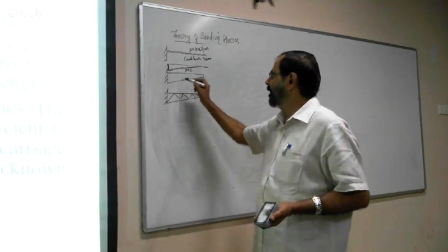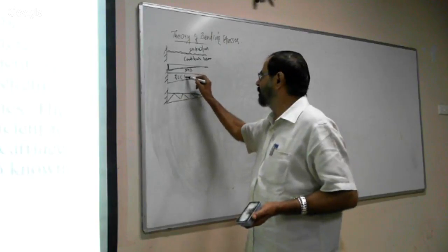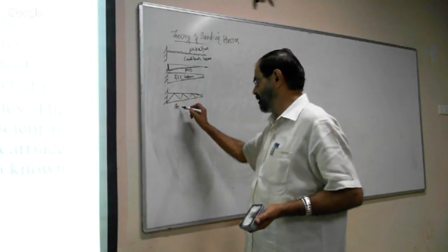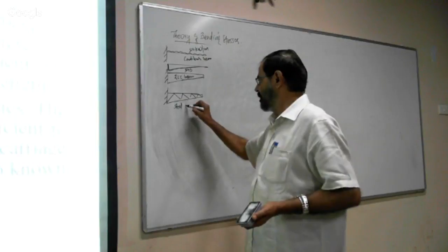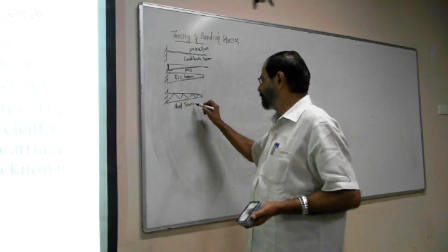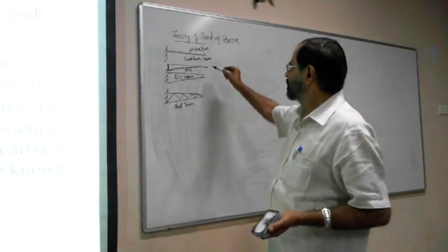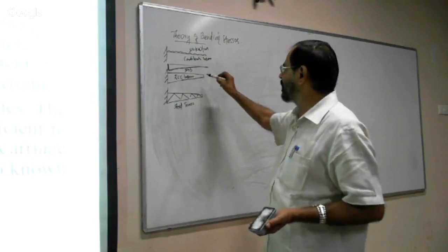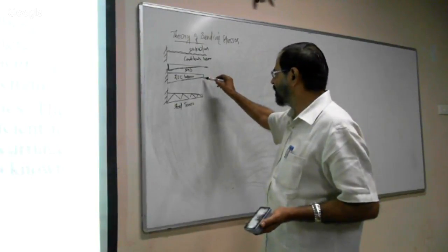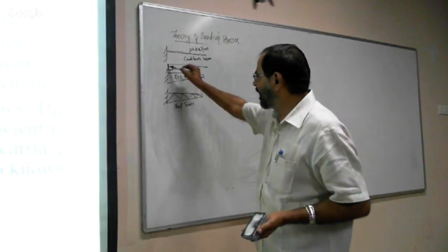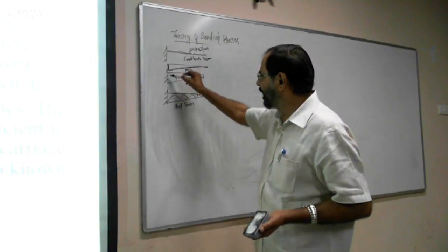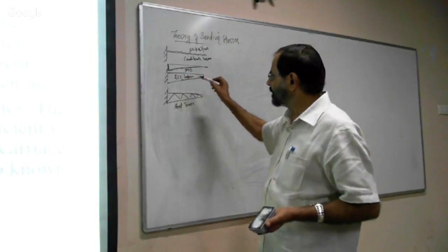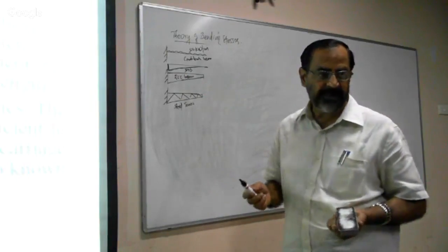Now this is the construction, maybe an RCC beam, which somebody may construct in front of your house. Now this is the steel beam, steel truss or beam, whatever it may be. Now see, here is zero bending moment, so we need zero section, but we can't create a zero section. Therefore, we will give the minimum section here, and at the support, where this is the maximum bending moment, we will provide the maximum section.